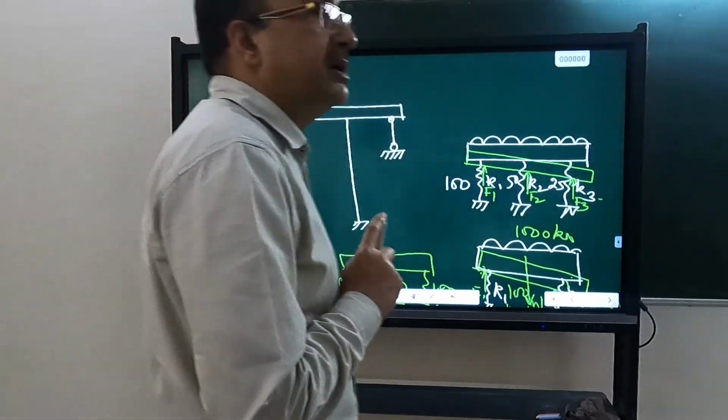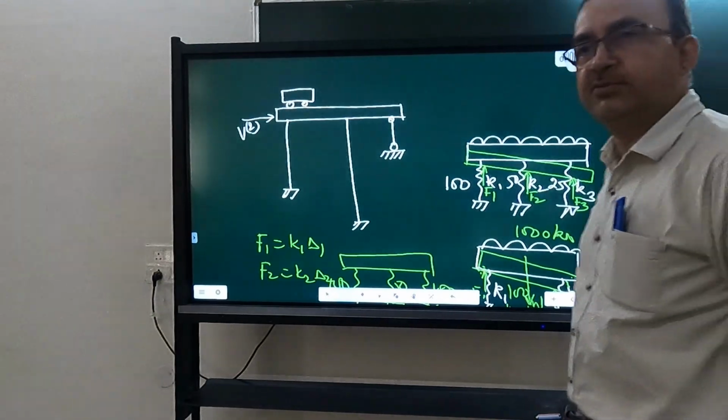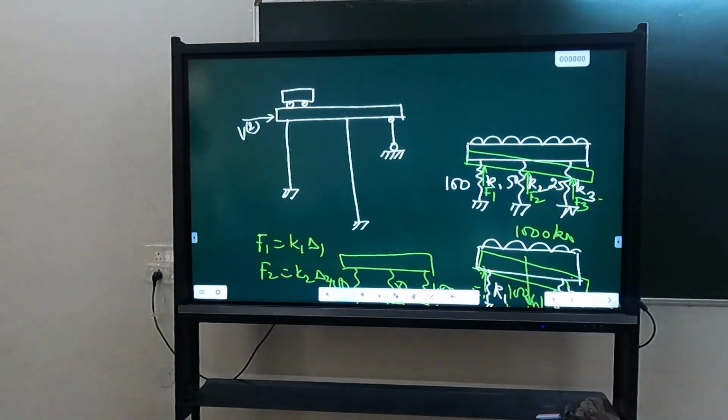What will happen to the ductility if the hinges are forming in columns? Ductility will be more if the hinges are forming in columns. Why you say so? Then we should allow plastic hinges to form in columns in buildings also? No, at the bottom of the column. If the hinge is formed at bottom of the column, then we get large deformation. So ductility will be more.